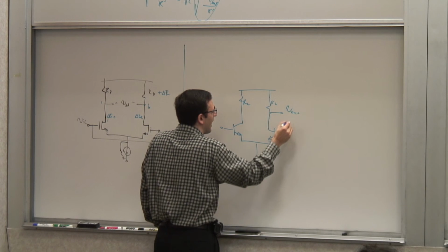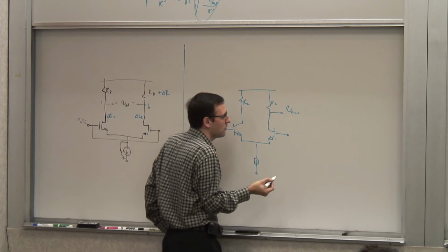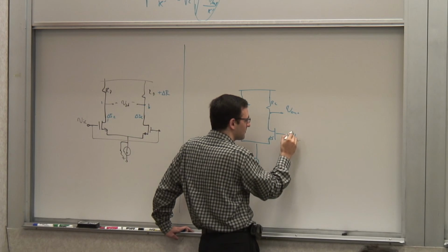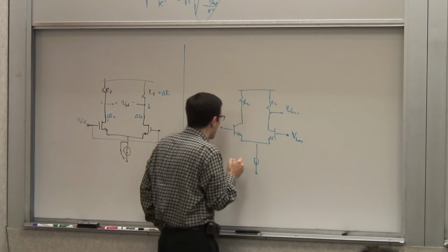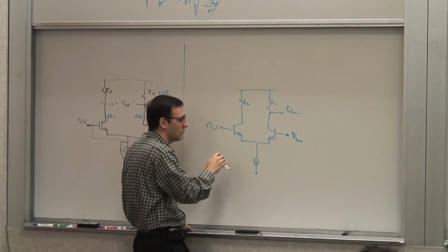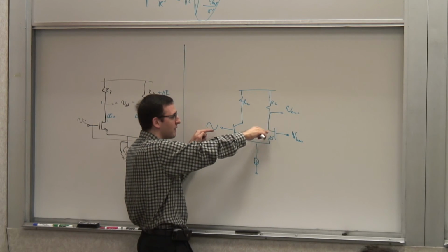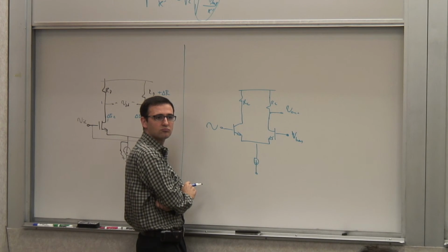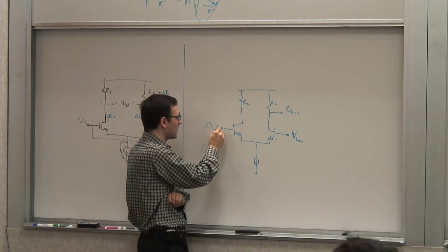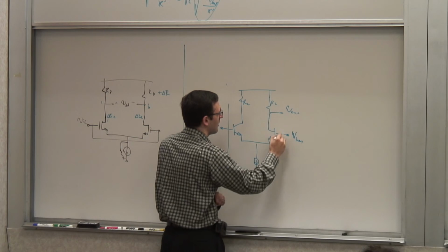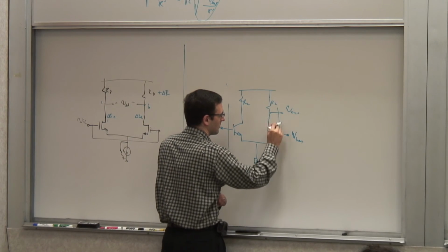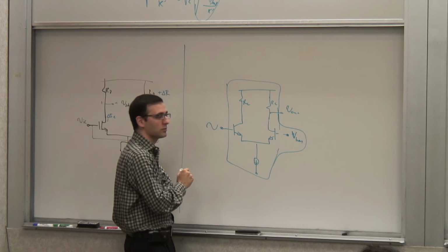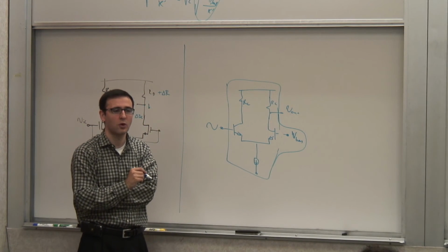So if this becomes V out, and then you can also maintain this voltage at some bias constant voltage, right? So let's say V bias. Now, if you apply a differential signal, it's the difference of these two. The differential part of it gets amplified here, and you get half of that at the output. Right? So you can actually think of this whole thing as a box, which is a single input, single output amplifier. You can always use it as that.